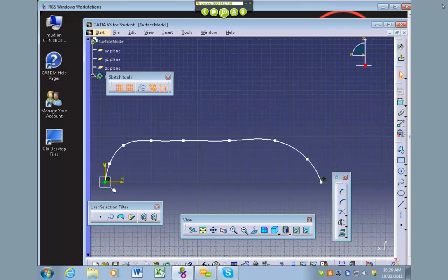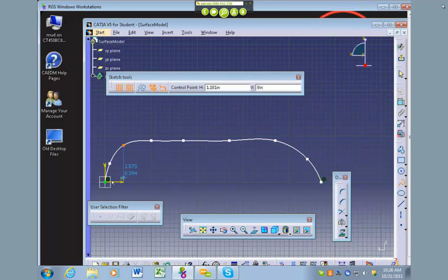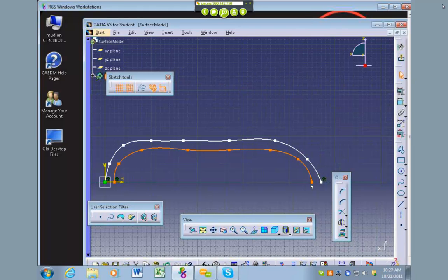Okay, so I did a spline here, kind of showing where the upper surface of my car is. We want to do another spline slightly below that one, and this will represent where the shoulder of the vehicle will be. About where the door would be, right below the driver's side window. The first one is just for the center of it.